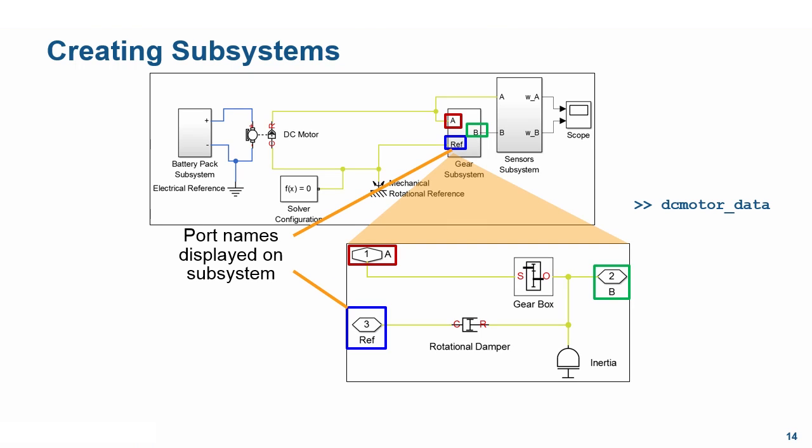We just saw how to make subsystems to make the model easier to read, navigate, and reuse components. This also helps us organize our model in functional blocks. We also saw that the data transfer across subsystem borders can be done through input and output ports, which are Simulink signals, and connection ports, which are Simscape connections.